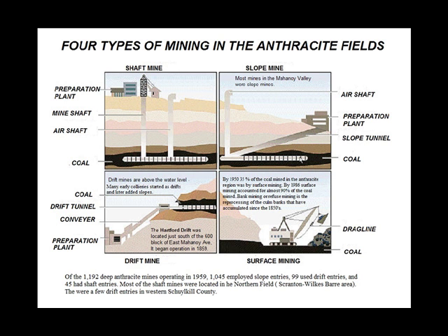Obviously, the shaft mine has the least amount of disruption on the overall structure because you have minimal disruption on top and then you mine and dig out below. One of the big issues, however, is that now you're creating large gaps in your rock and this can destabilize the area. Your slope mines and your drift mines are compromises.